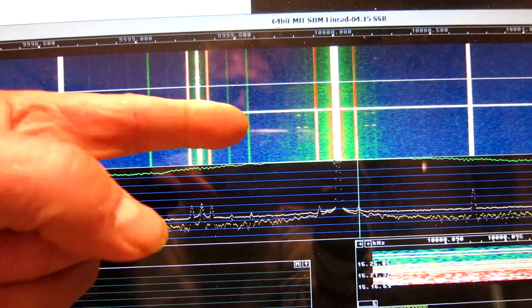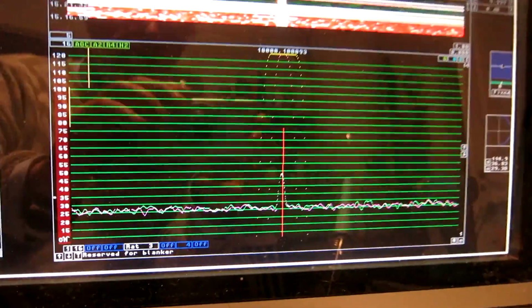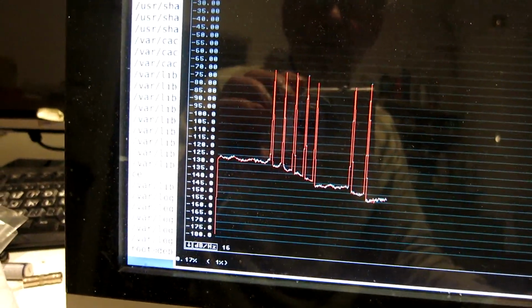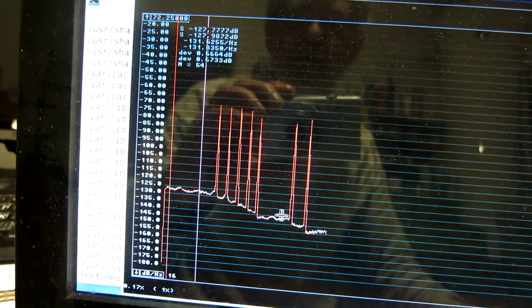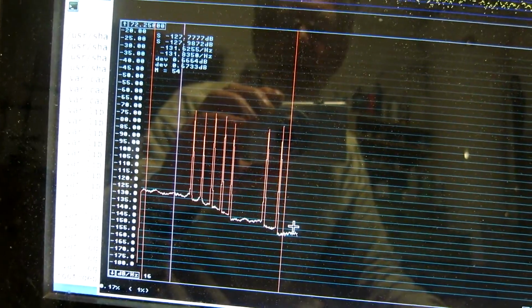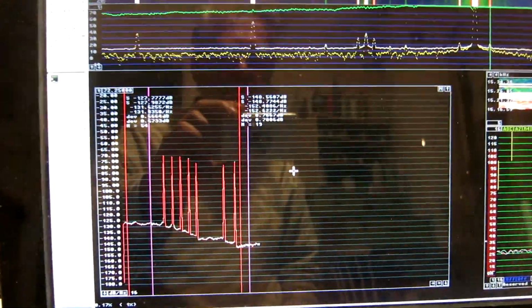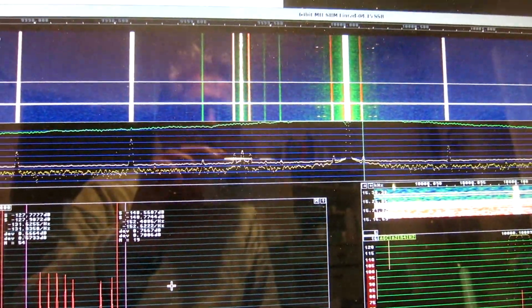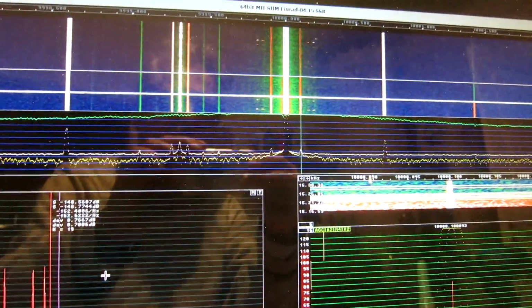So here is 18, 21, 24 dB. And the 100 Hertz modulation is still pretty strong. And I'm looking at it here. At 3 dB, the level was minus 127. And at 21, it is minus 148. The difference is 21 dB, and that's the difference in power into the crystal. So this is a linear phenomenon, which the noise is not.